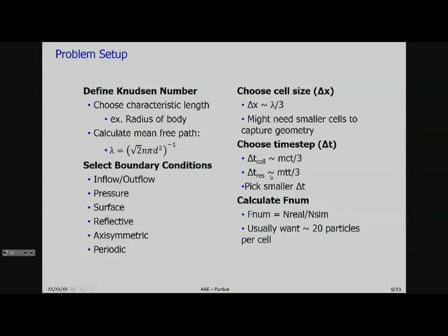So you don't want a particle to jump through multiple cells in one time step. Again, that's taking one particle that has its internal energy profile set in its first location and then moves to a completely different location. So that could be violating your conservation of energy again. So you set these conservative parameters here, and then you pick the smaller time step.